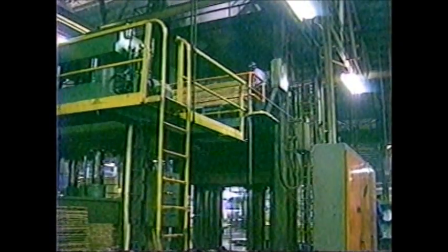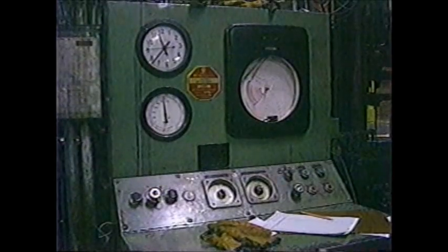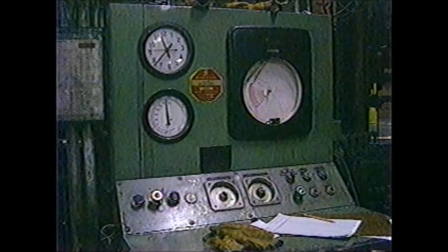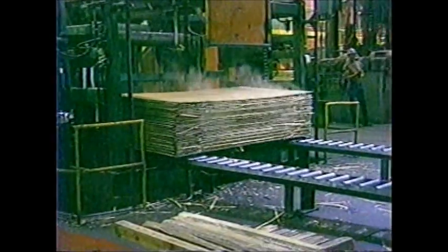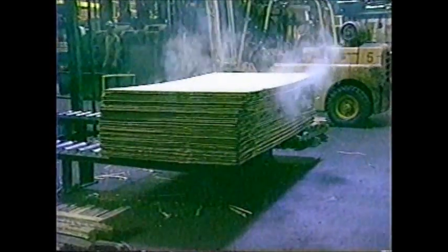After pre-pressing, the panels are loaded into a hot press where the panels are subjected to temperatures of 300 to 330 degrees and pressures of 300 pounds per square inch for about 30 minutes, depending on the number of plies and panel thicknesses. The press opens after the panels have cured under heat and pressure, and the rough panels are automatically pulled onto an elevator. The stack of panels, called a hot stack, is removed from the elevator conveyor and set aside to further cure and cool.